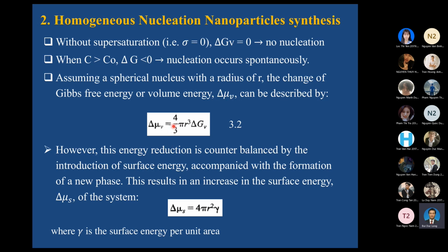It means that when the particle is formed, more surface is formed, and this introduction of surface energy costs energy. Still, by the formation of a new phase, we can reduce the energy of the system, so the system will be more stable.